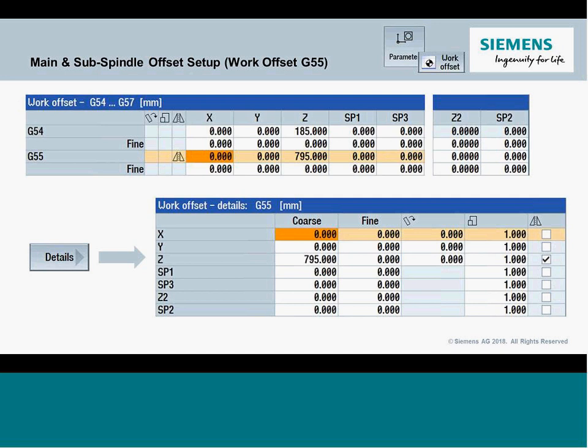I can still methodize everything as if it's my main spindle, and then when I apply it to the spindle, it calculates the appropriate orientation angle it has to drive the B-axis to, what it has to do with the live tool as far as positioning of my gamma, and then additionally, where offsets are, what direction the Z is moving in. So all that's being handled by a simple mirroring of the Z-axis. So it dramatically reduces the complexity of programming, switching between main spindle and sub-spindle and all that kind of stuff.